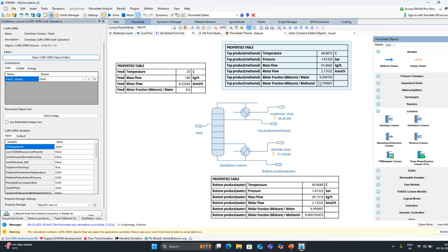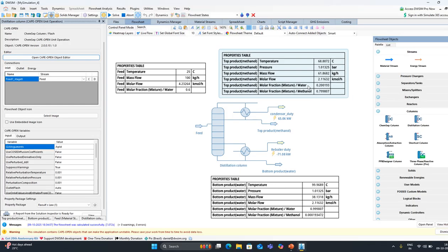Next thing, we are going to learn how to separate this mixture more using different simulation techniques, because you can see here how much I am increasing the reflux ratio. It is just slightly increasing the molar fraction, but here we can get pure water. But here we are getting a little bit of water because at the top also in these pressure conditions we might get much more water. But second thing I can do, I might operate my column at higher pressure, which are the different things that we can use. But the sole purpose of this video is to learn how to simulate a ChemSep operation for the distillation column. So this is just about the setting up.